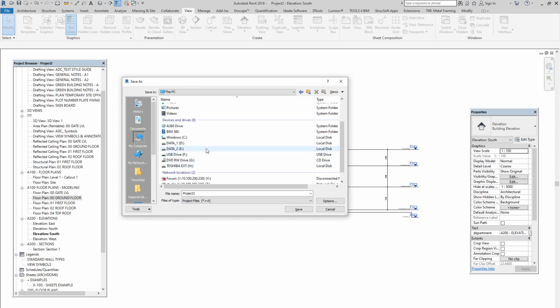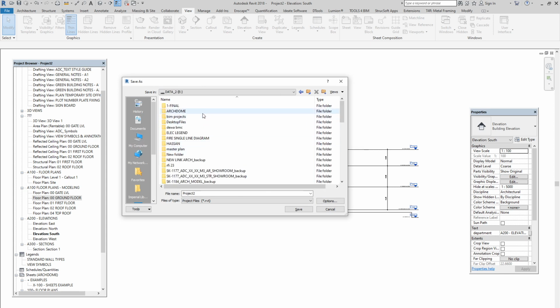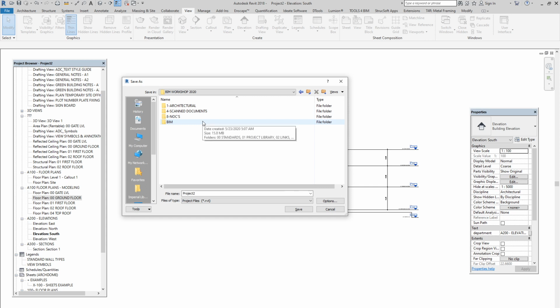Okay, for our company server, we will start saving into the project folder itself, the project folder which is BIM. Okay, and here I have architecture, structure, but now where do we have it? We agreed that this model will always be like a link model. So we will go to the links folder, and we have RVT links, Revit links. Okay, we will just place it here, but we have to give a proper name. This is very important. Instead of this, I will type the proper name,